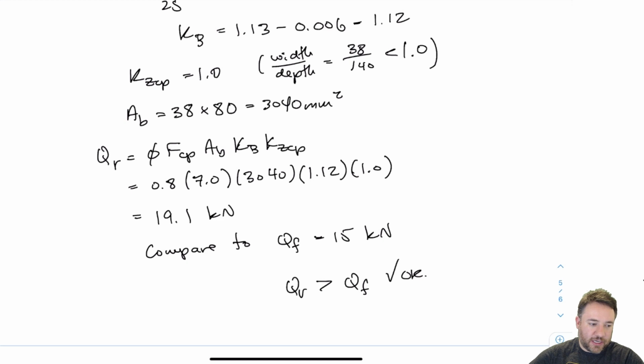So now by this point, I have checked every single resistance in that assembly. All the resistances of the beam and the resistances of the joists that are sitting on top of the beam. And so hopefully that gives enough varied examples that we can see all of the different things that we might run into when calculating bearing resistances.